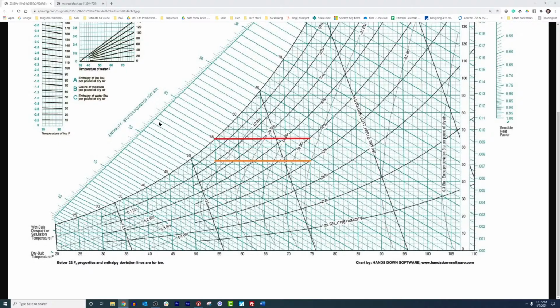You can also look at space humidity and return air humidity and use that to drive your economizer. It also depends if you have a way of removing moisture in the airstream and whether this is 100% outdoor air or it's a mixed air unit. So assuming it's a mixed air unit, and assuming you have to keep 5-10% damper position open in order to satisfy ASHRAE 62.1, then in reality, from a moisture control perspective, you can add a desiccant wheel.